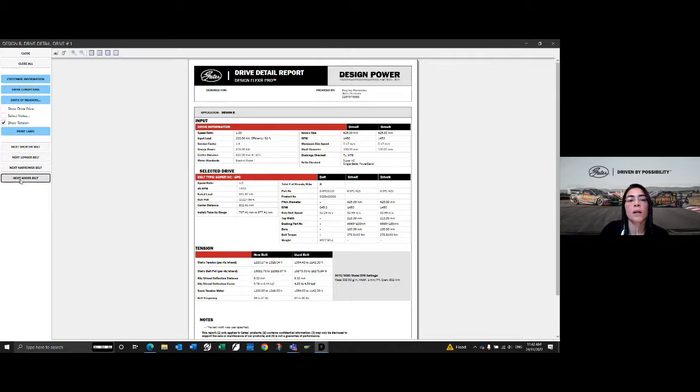And then you say, all right, I want to use one more belt, and you select wider, and it will include one more belt. So this one will be a solution for the customer. So you have 8 belts running on the same pulley. I don't remember how many grooves you have in the other one, but that one could be a solution for that customer.